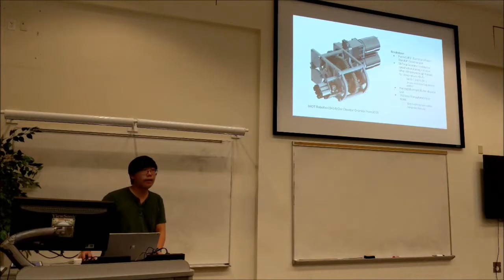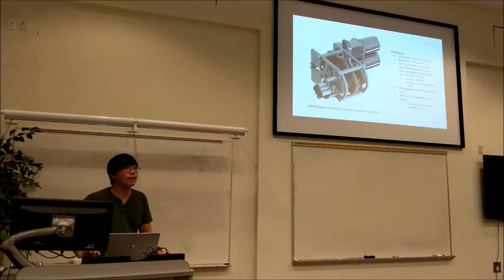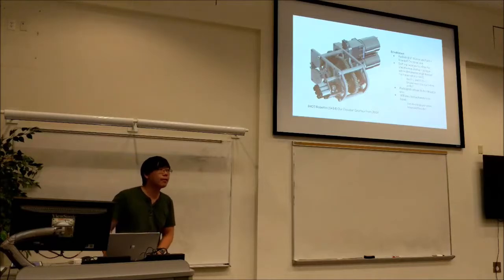So we use pocketed quarter-inch aluminum plate again, and then we use standoffs to hold the gearbox plates together. The reason why we designed this gearbox is because for our elevator, we wanted the ability to shift between two speeds. The reason for that is so we can place the cube faster, if you guys remember that game, and also climb with 3 robots. We never actually ended up doing that, but we wanted the capability to add that on.